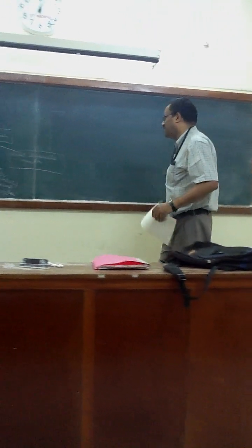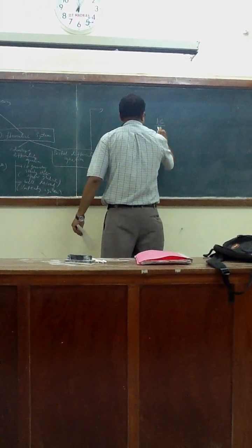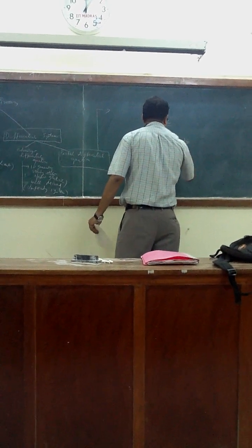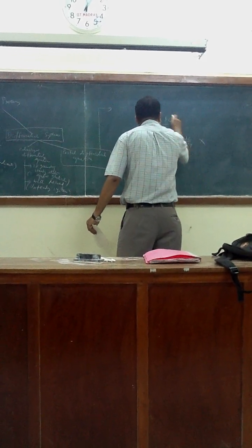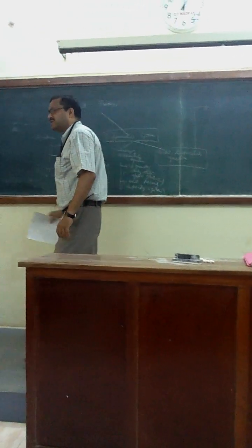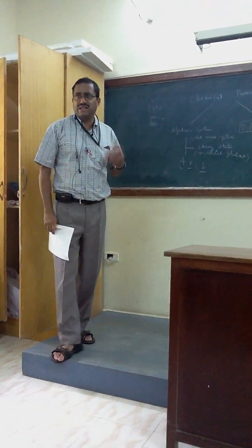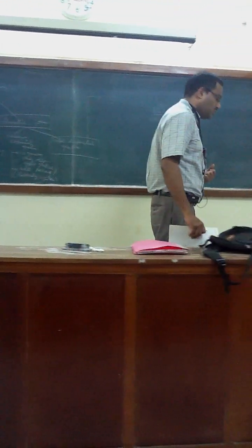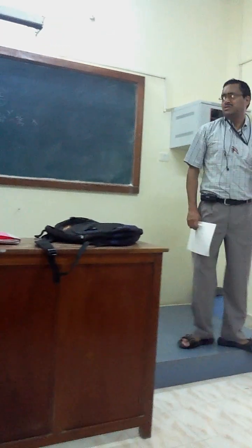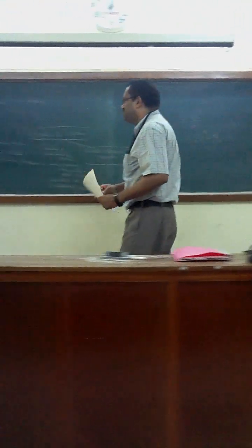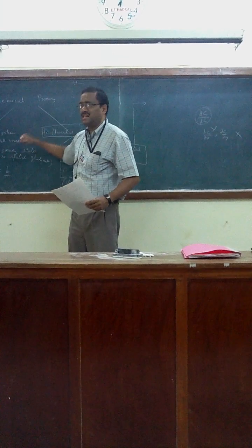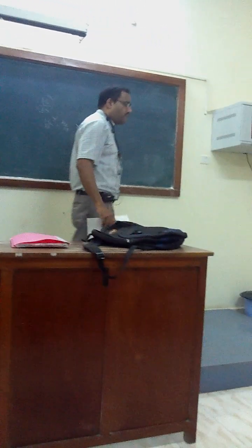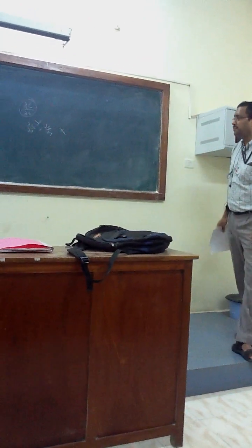That means you are having a derivative like this, dc by dt. dc dx, dc dy, they are not there. Only this derivative is there, even for a well-mixed system, because it is an unsteady state system. Well-mixed unsteady state system. So here you saw that a well-mixed system, steady state, is always algebraic, but for a well-mixed system, if you have unsteady state, you get an ordinary differential equation. Okay?